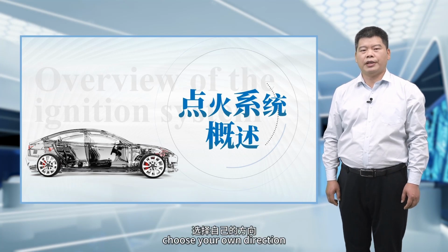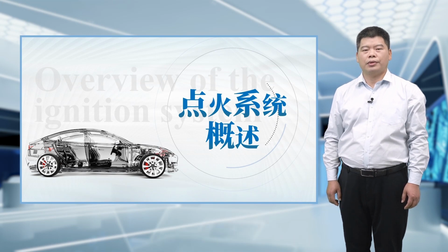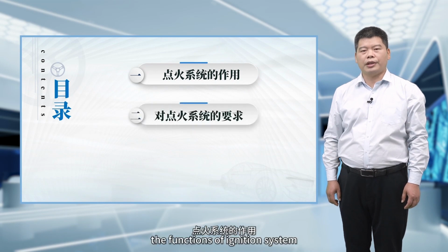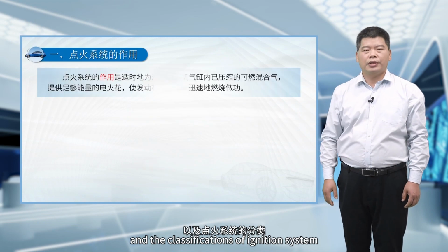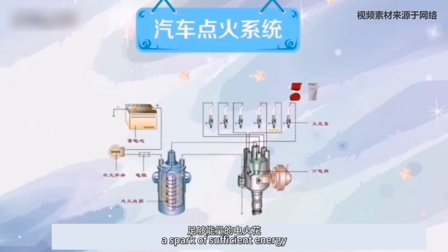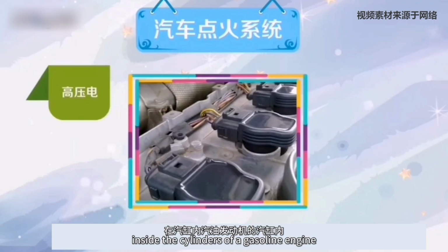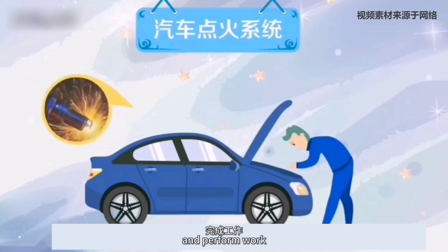Choose your own direction. In this lesson, we will study an overview of the ignition system, primarily focusing on three aspects: the functions of the ignition system, the requirements for the ignition system, and the classifications of the ignition system. The purpose of the ignition system is to timely provide a spark of sufficient energy for the compressed combustible mixture inside the cylinders of a gasoline engine, allowing the engine to combust rapidly and perform work.